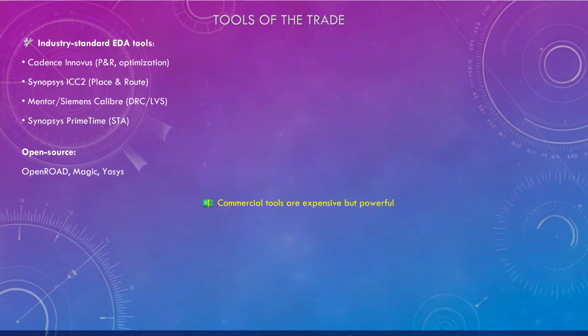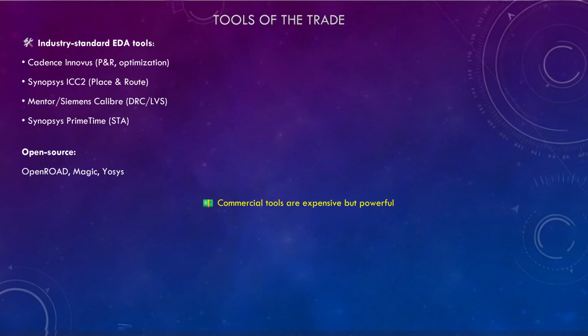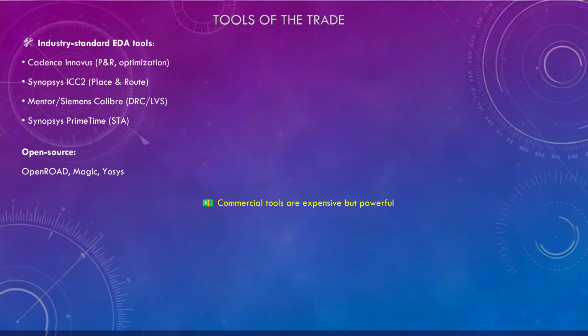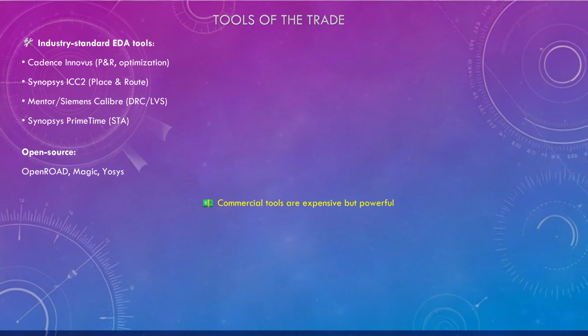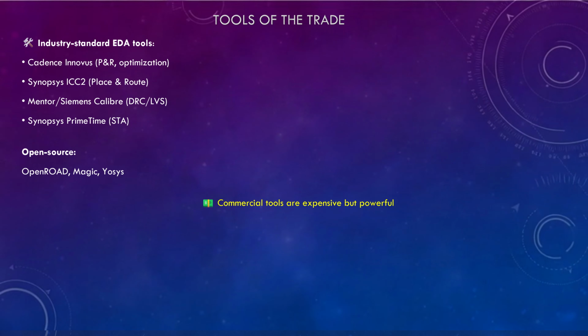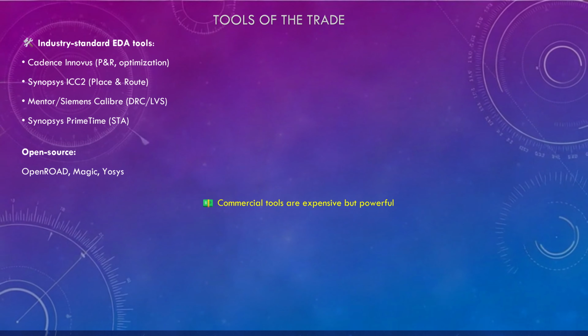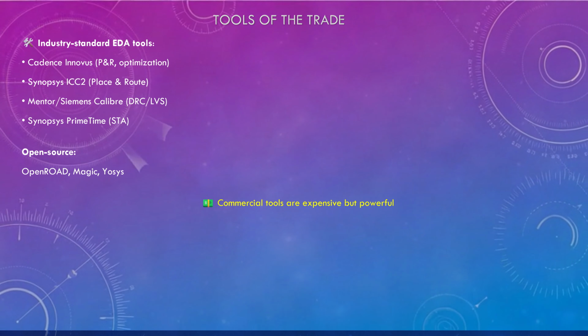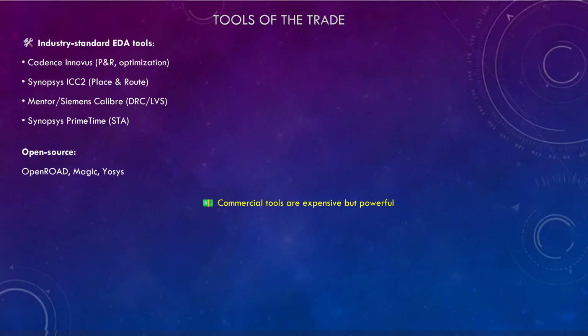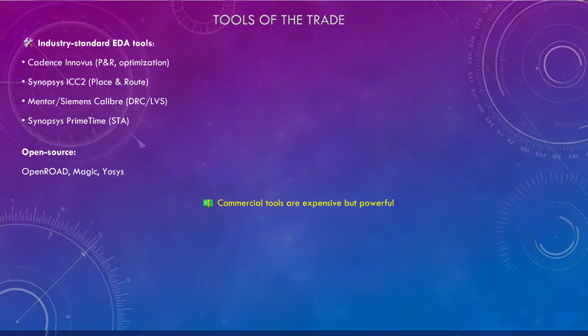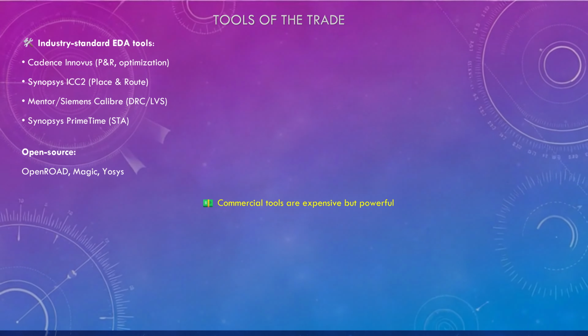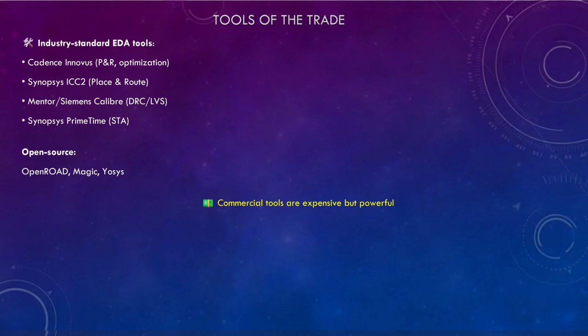So for learners, open source alternatives. OpenROAD for complete flow, Magic for layout editor, Yosys for synthesis. Pro tip, learn on open source tools first, then transition to commercial tools in industry. Most companies use Cadence or Synopsys. These are industry gold standards.